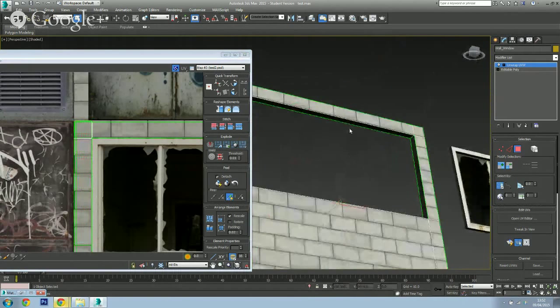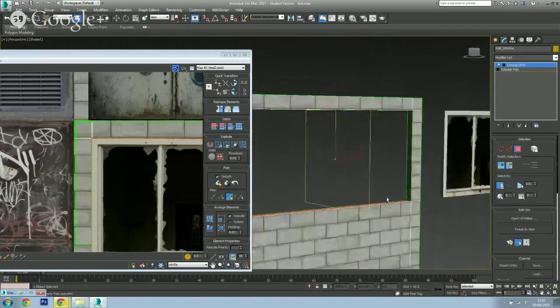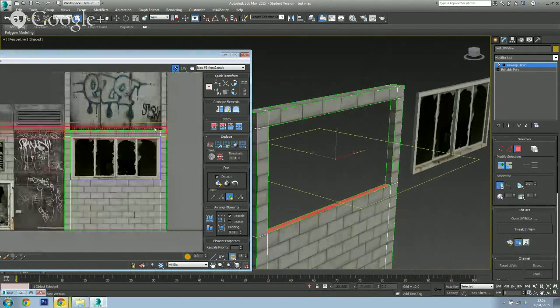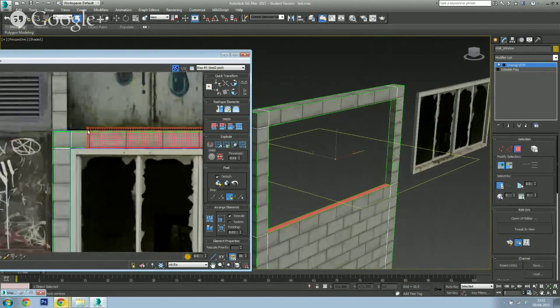And then finally, we've got tops and bottoms of the inside of our wall here. Again, we're going to need to change the direction of our quick planar to Z. And here we are. Here's our piece that we're going to resize. So it's quite simple. I think you guys will find it easy. When you start doing it, you'll find it easier to actually do it. So let me just line this one up.